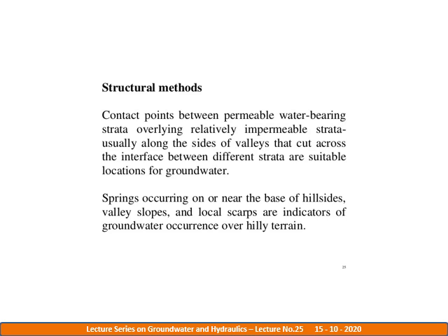The penetration depth of electric method measurements depends on the resistivity of the subsoil, the distance between transmitter and receiver and the operating frequencies.